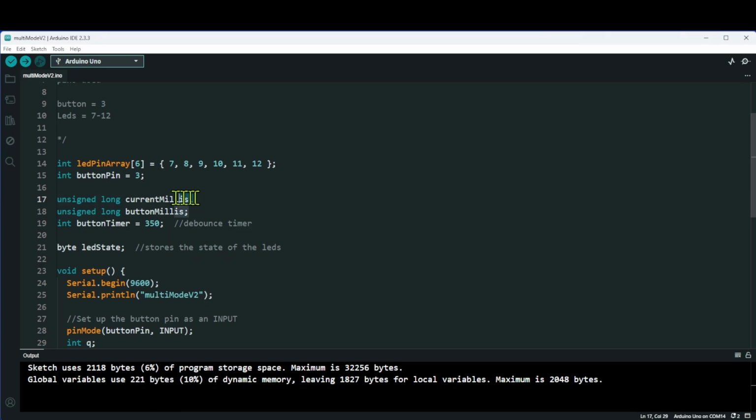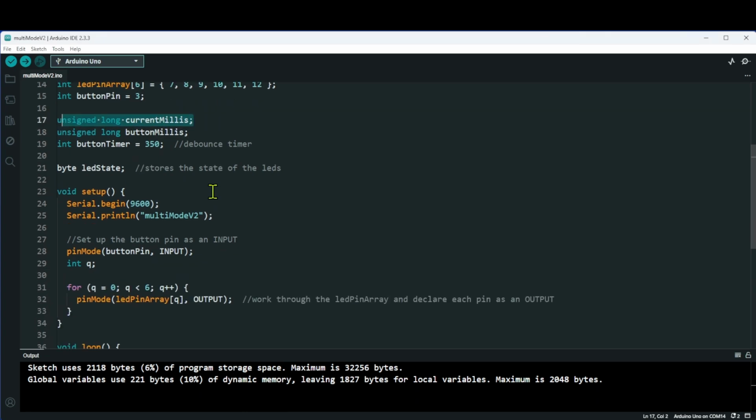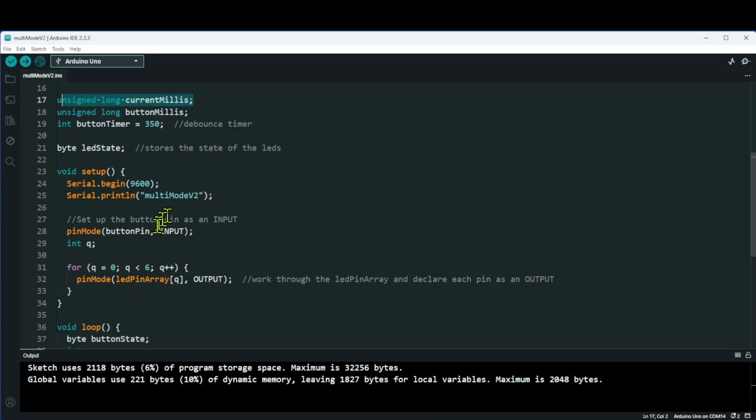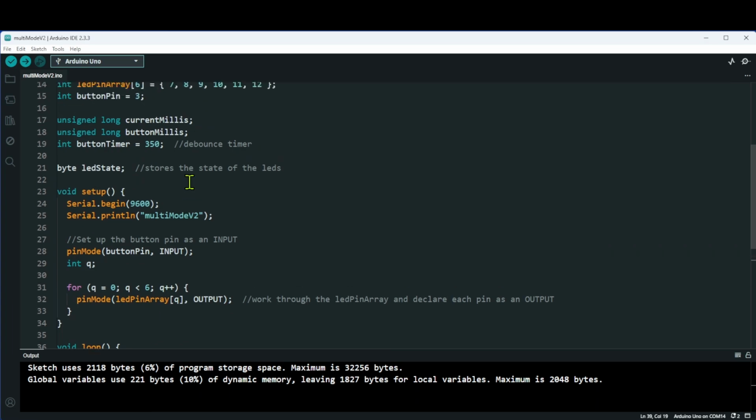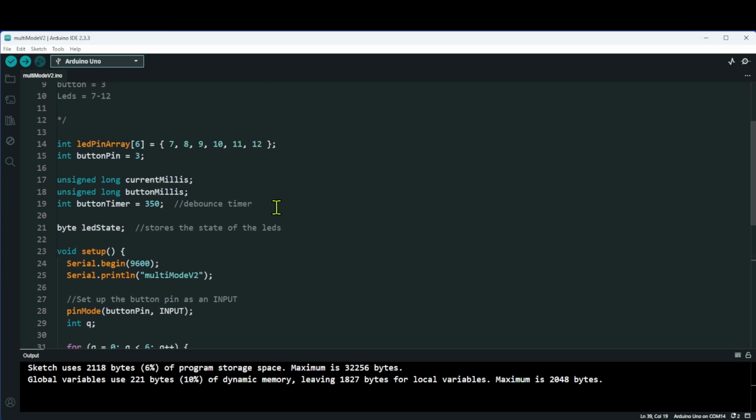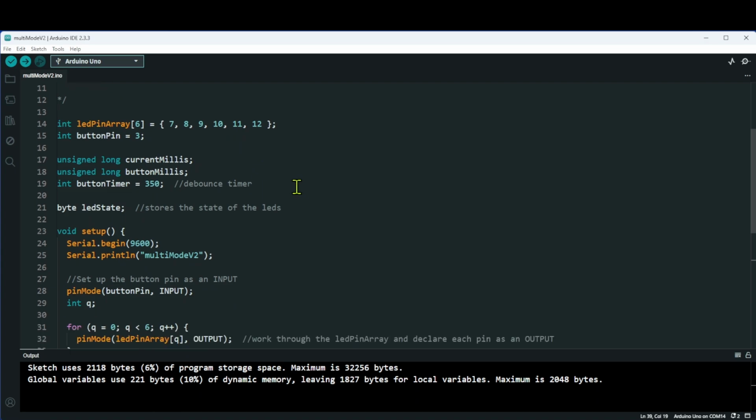As always, the sketch is using current millis. All the timing in this sketch is done using millis. If you start to use delay in your code in any of the examples I am making today, you will trash the code. Get rid of delay from your code unless you're just using it in the setup for some basic setup issues while you wait for things to initialize.